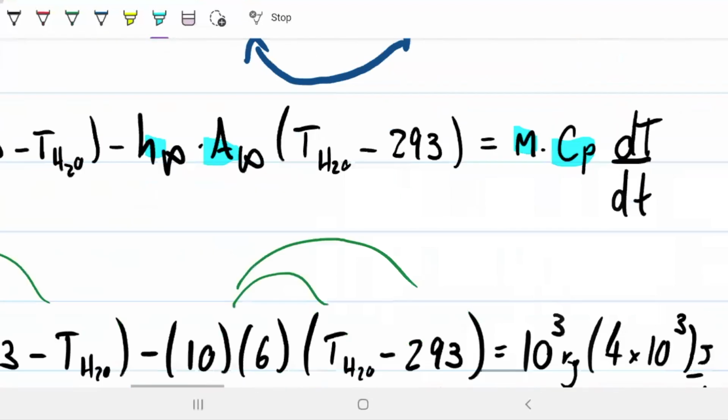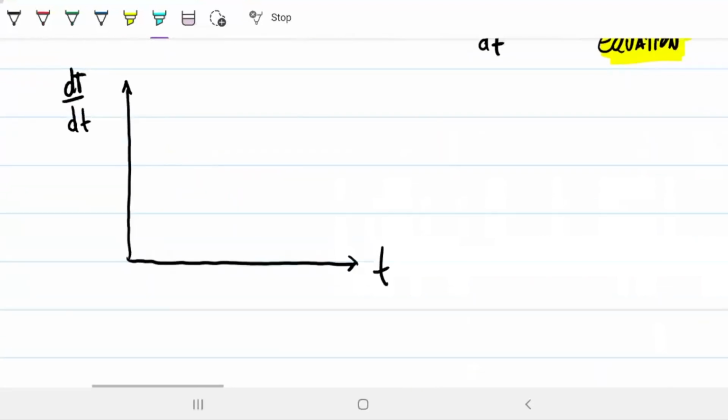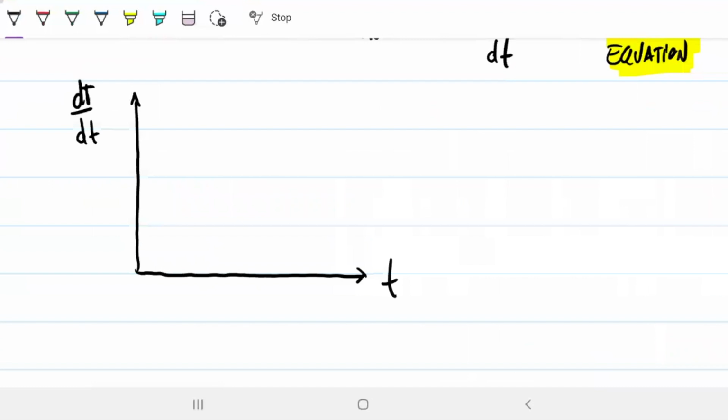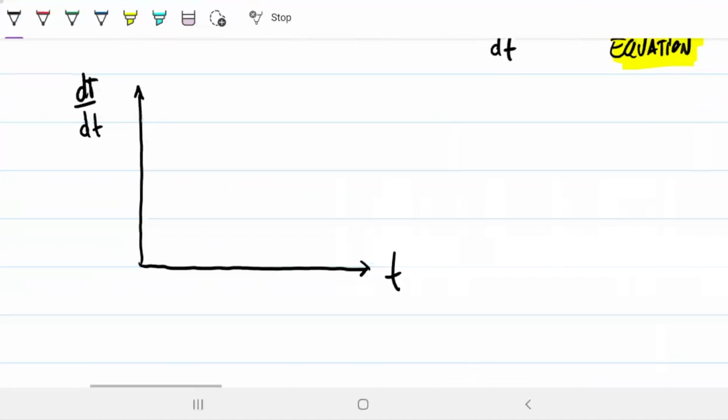Okay. So what does that mean? Well, let's think about it for a moment. How is the temperature of our fluid changing as time elapses? In the beginning, there's no Q out, so we have a big temperature change, right? It's going to increase fast because our delta T in relationship to the steam is high. So our dT will be somewhere on the top there.